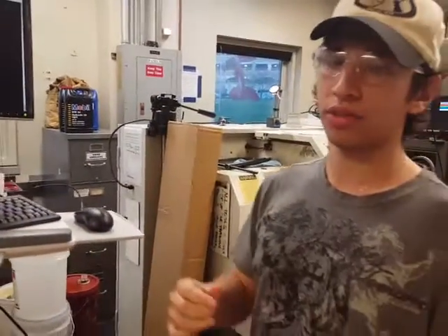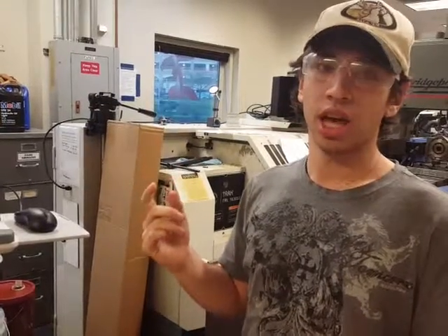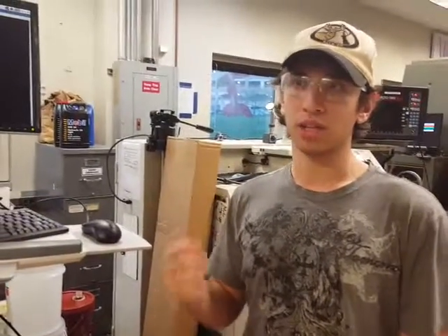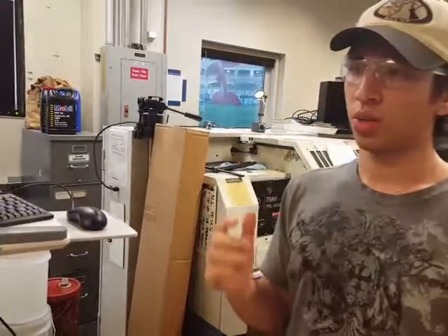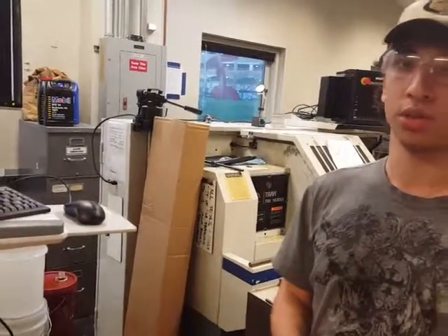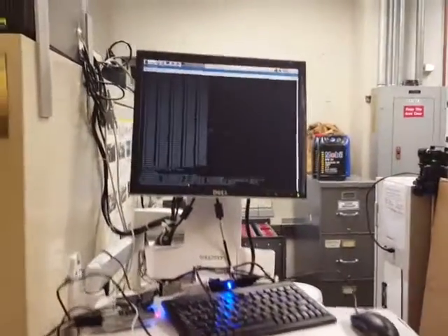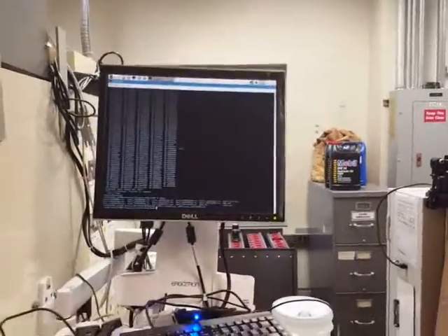Basically, what this does is it takes the serial data you have and calculates estimated times for when each instruction is being executed, and then maps that to the spectrogram data. Then you can get the magnitudes and the frequencies and figure out which instructions are causing the bad noises, and then you can adjust your feed rates accordingly. And so now it's done, and we can view the new file.